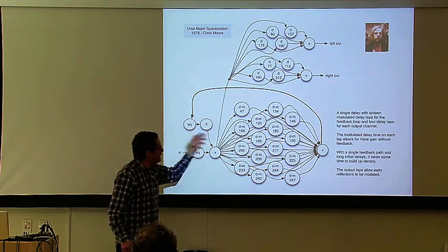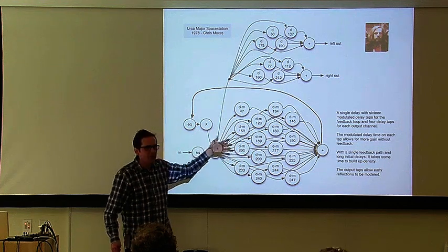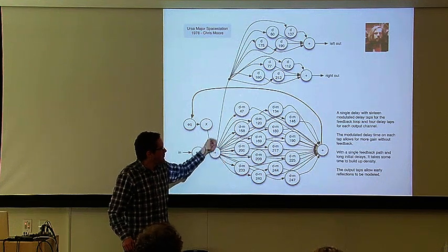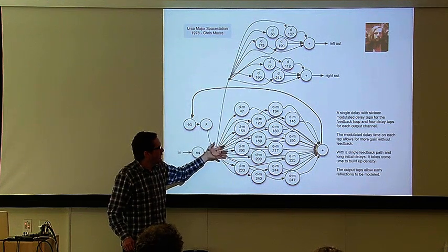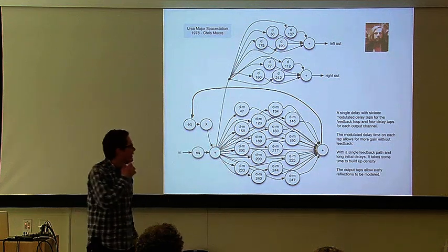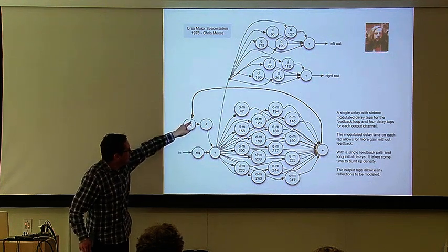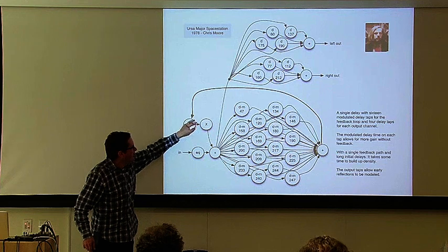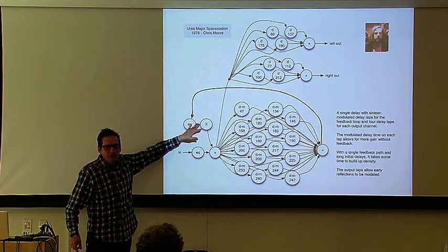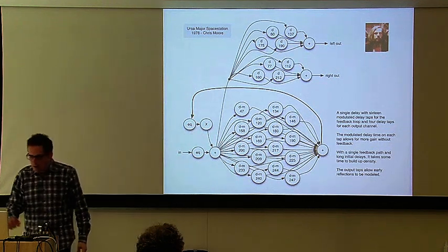Okay. The other big innovation, Chris Moore's big innovation, was that all of these delay lines are modulated. By doing that, we no longer have tones building up, so we can actually now get more gain through this network without feeding back on any prominent tone. And he also added full EQ sections in the feedback network, which in his original device were all analog. So it also had a bit of natural saturation in there.